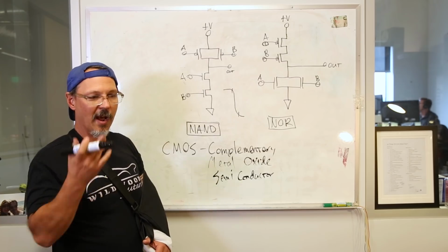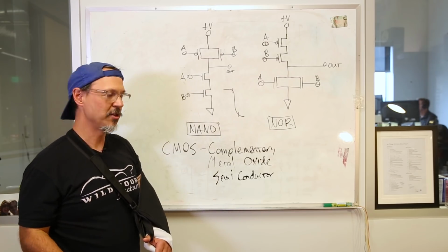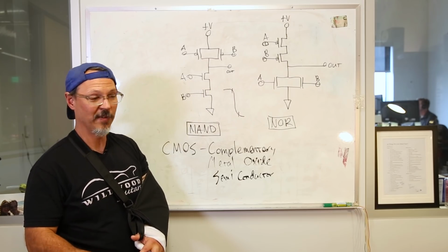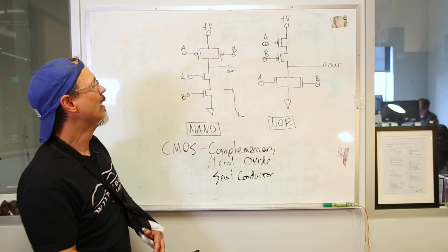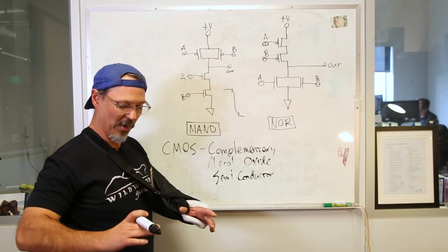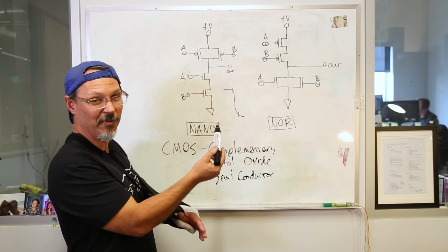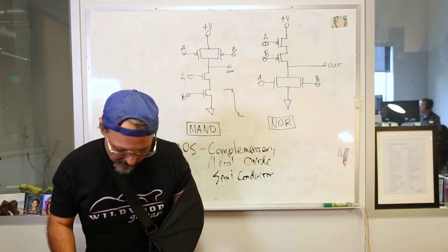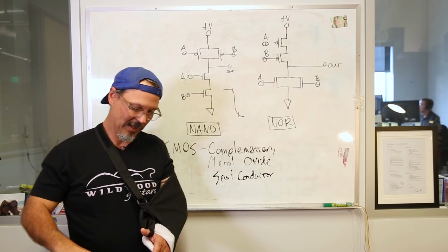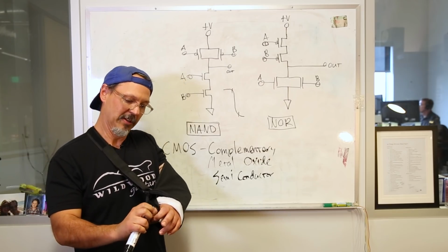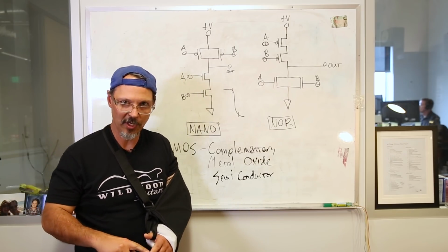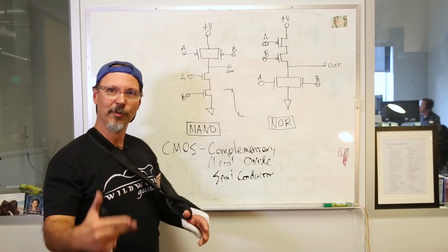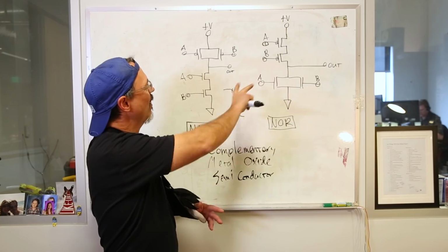But it is a method of fabrication that allows you to place P-channel MOSFETs and N-channel MOSFETs on the same die. And so all of this stuff gets put on the same part, and it scales really well because they're only putting these parts down. So it has enabled us to make all of our logic gates into a monolithic part like that, or build an FPGA or a microcontroller or a microprocessor, or all kinds of really crazy things that incorporate all of this stuff.